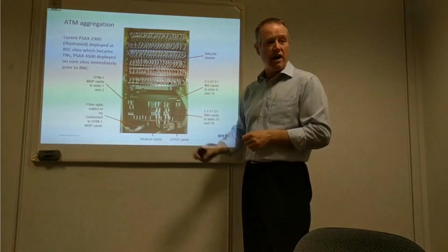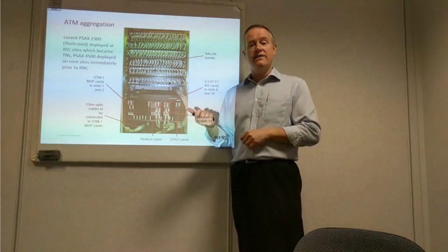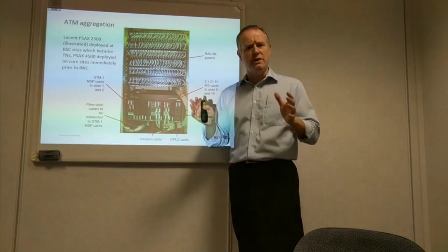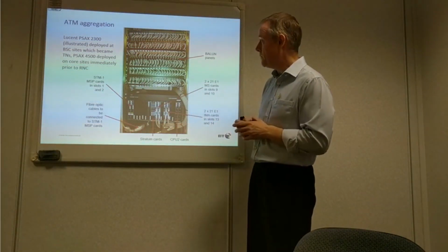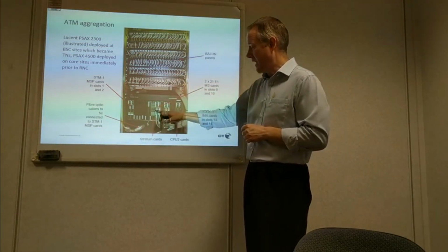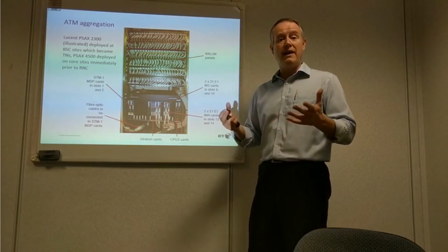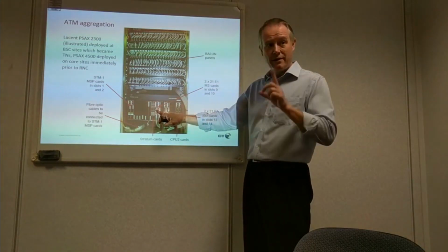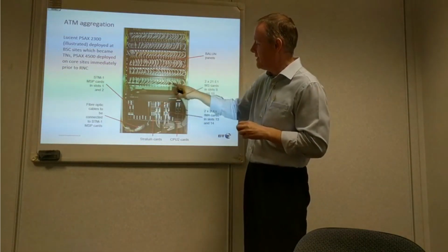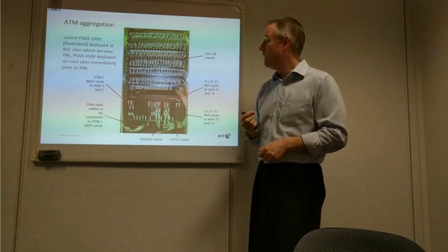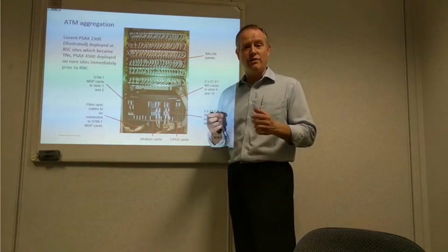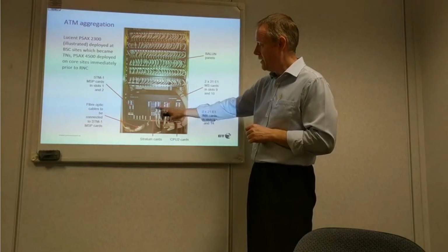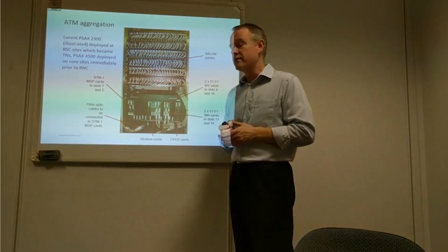We've also got some multi-service cards here, taking the Abis and Gb interface and actually emulating those over the ATM network as well. So we're building a truly converged 2G, 3G network. And you can see lots of balance panels here because to get this density on the cards, they used balanced 120 ohm interfaces, whereas the interfaces here are unbalanced 75 ohm interfaces on coaxial cable, effectively. So we need to convert between the two, which we do via the balance panels itself. So 120 ohm balanced, 75 ohm unbalanced on the coaxial interfaces.